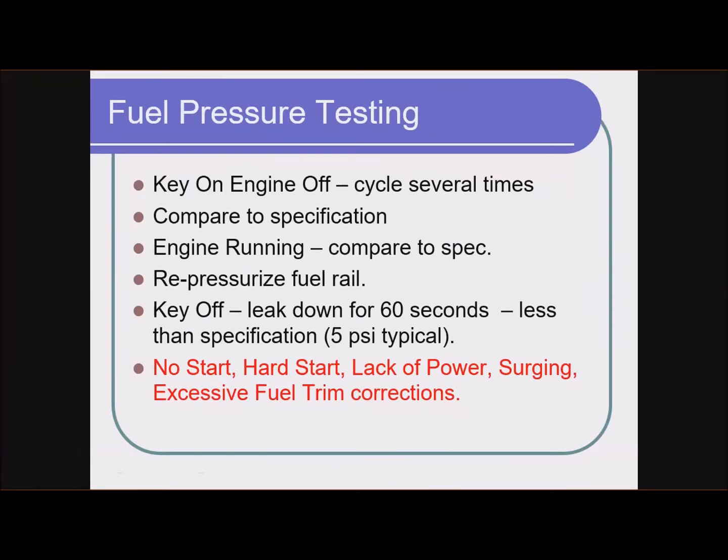The other thing could be any kind of a pressure leak. So fuel pressure regulator, an external leak, a leak in a line, injector O-rings, whatever. Well, not injector. Yeah, top injector O-rings could do it. So if you see this leak down, that could explain a hard start problem. And so you have to try to figure out where that leakage is.